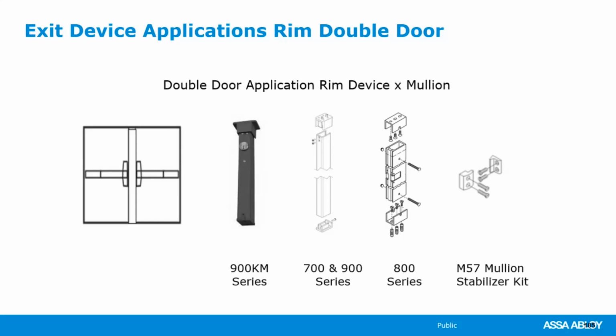We're going to talk about our Pullman latch versus our secure bolt latch and why I would recommend that in addition to pretty much eliminate the possibility of someone being able to rock a door open. We see that more with devices that do not have a dead latch feature. On the aluminum storefronts, where sometimes the aluminum manufacturer will supply their device, and their device may not be much more than that 500,000 cycle type device that, again, I wouldn't put on a heavy use application, but sometimes it gets negotiated in. Those ones don't feature a dead latch and they can be popped open pretty easily. So that's our opinion. Rim by mullion is the best way to secure that opening.